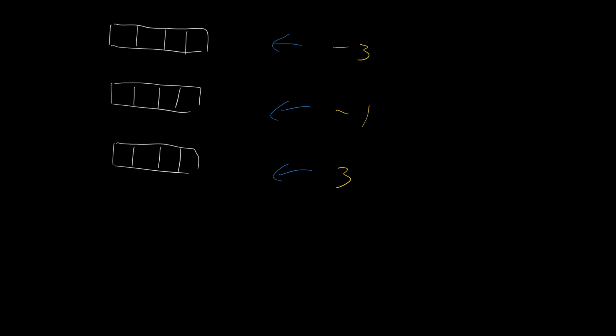Once again, there's an infinite number of ways of doing this, but the convenient way of doing it is using 2's complement. For reasons that will be explained shortly, we're going to store the number -1 as 1111. The number 3 is stored as usual, 0011.